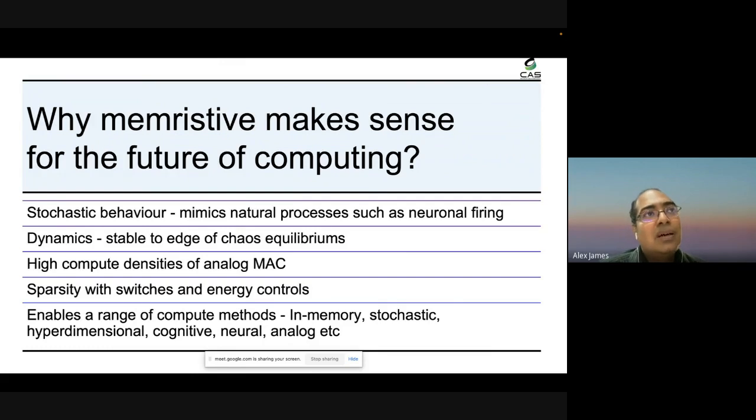But there should be some very basic properties that need to be obeyed for you to call the device a memristor. And beyond that, a lot of the other properties may vary from one device to another. Now, one thing you could look at is the dynamics of the device itself, which is extremely interesting. You can create a whole definition of complexity through edge of chaos, and looking at the equilibrium points and other things. You could generate patterns. You could create different kinds of filters. All with a set of a few memristor devices, you would be able to do that.